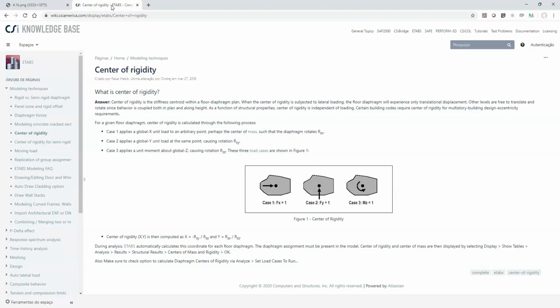Although these loads could theoretically be applied at any point on the structure, the method applies them at the story center of mass. Determining the rotational stiffness for each story is straightforward because we can determine it from the relative rotations caused by the rotational load. Since a moment creates the same rotation regardless of where it is applied, the exact point of application is not important, as long as it is applied at the story level. However, when we apply a horizontal load, the point of application is not irrelevant when we are trying to determine the translational stiffness of that story.